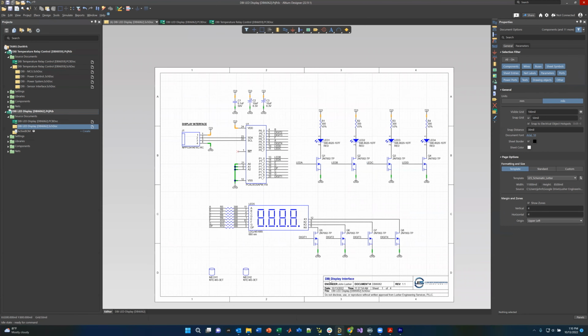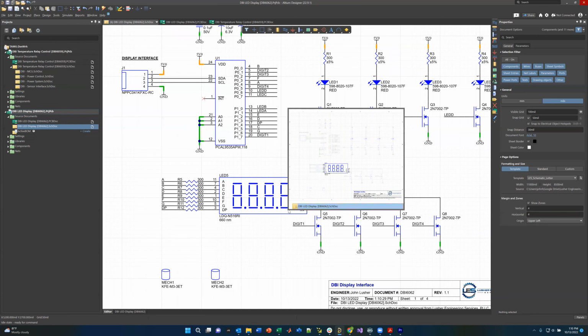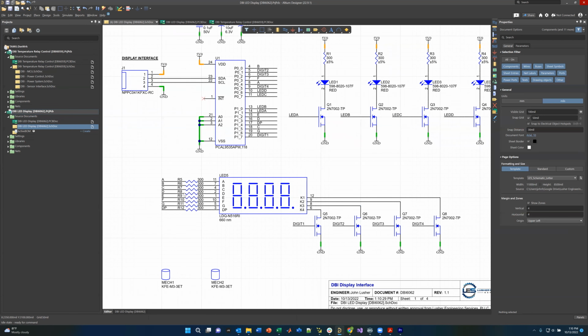And we have a 7-segment display. Just so you know, with 7-segment displays you're driving one digit at a time, and you have to scan it. So the microcontroller is constantly driving this display to keep the LEDs on long enough that visually it looks like the numbers are always on. In reality, digit 1 is on, then digit 2, then digit 3 and digit 4, and then it recycles. Whenever a digit is not on, it is actually all off.